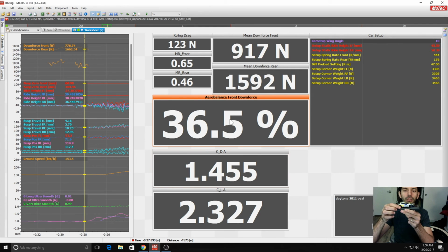So then that means that you would basically have an understeer condition in high-speed turns, and in low-speed turns you would have oversteer, which may or may not be a desirable quality, depending on the racetrack. So that's the case here. We have a lot of rear downforce, and these downforce numbers, again, are very reasonable compared to data that I have for older cars. That means that over the last decade and a half, quite a lot of progress was made with these GT3 race cars, which makes a lot of sense.